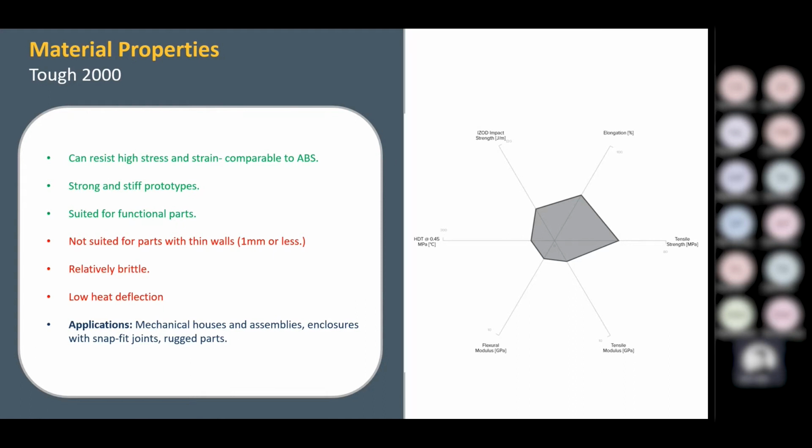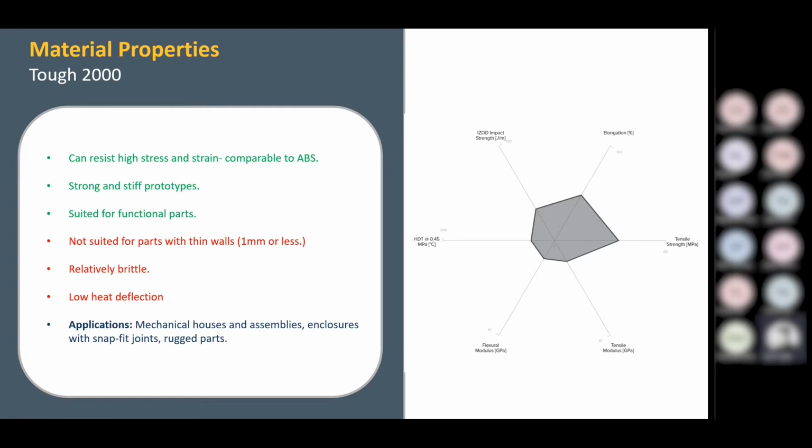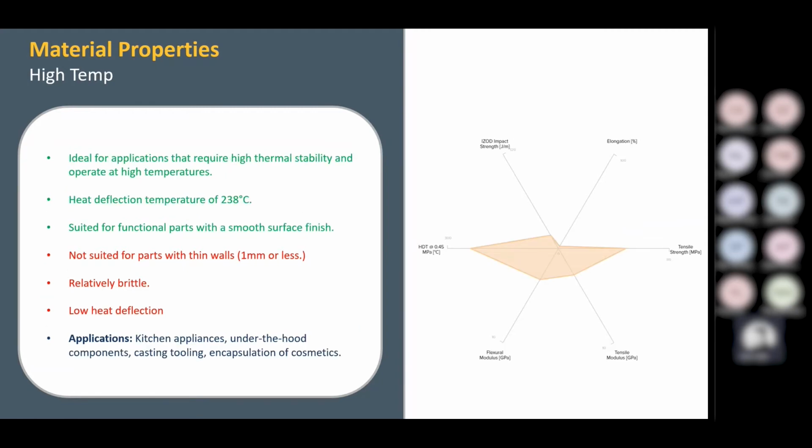So in terms of making a model, you'd scale your 3D model down first. You would then check your entire model to make sure everything's at least 1 millimeter thick. You would then think, do I need to divide it up further? For instance, if I was 3D printing the room that I'm in now, typically I'd probably want to take the ceiling off. Otherwise, it's going to fill the entire room with scaffold. So it's going to be much easier to print the roof separate and just stick it on after. So again, things to consider.